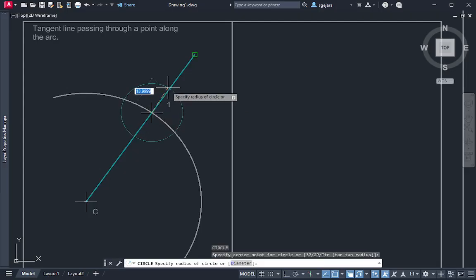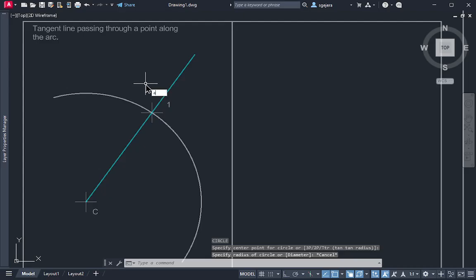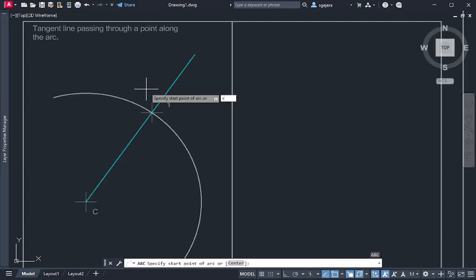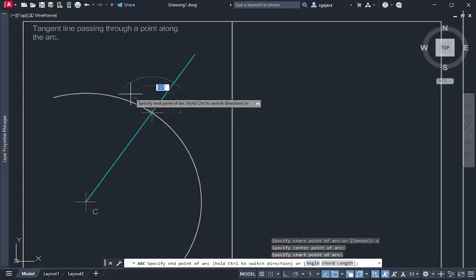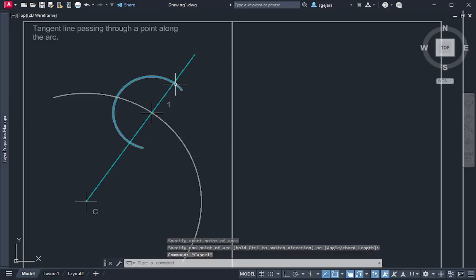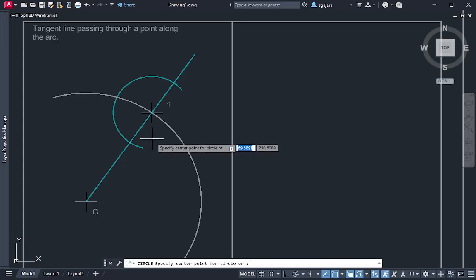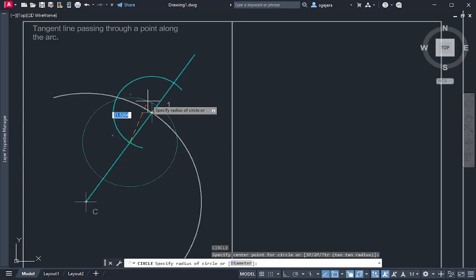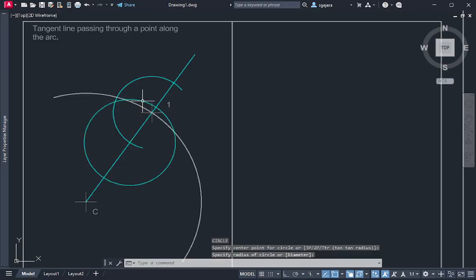We'll make our pseudo endpoints. You can use a circle or an arc. To keep it from looking too messy, I'll just use an arc. So, I'll press A, then C for center, then click it here. Then, I'll just mark 2 endpoints, this one and this one. Now from here, I can create a circle that is slightly larger than the midway point, like so.